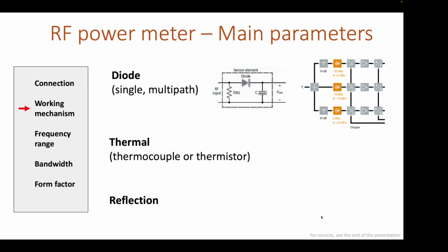Now, a completely different family of power meters is based on a thermal process, either by a thermocouple or by a thermistor. So how does that look? Actually, we would have the source heating up a resistor, the sink, which is a load of, for example, 50 ohm, and then we would have some element which is sensitive to temperature. That will be the basis of our measurements.